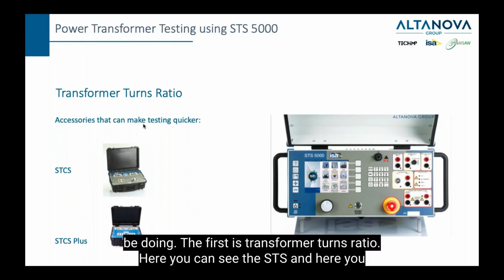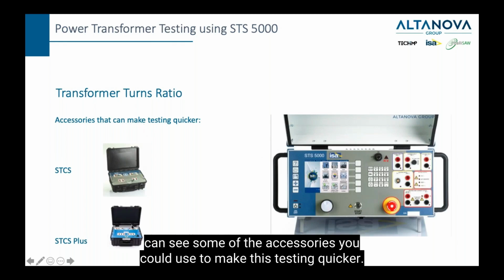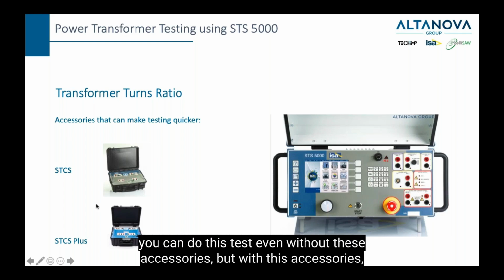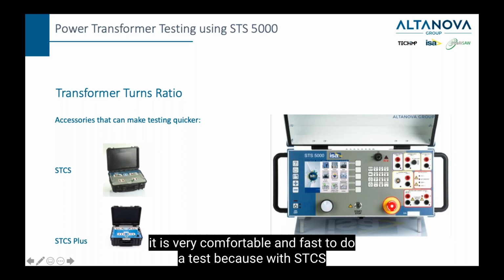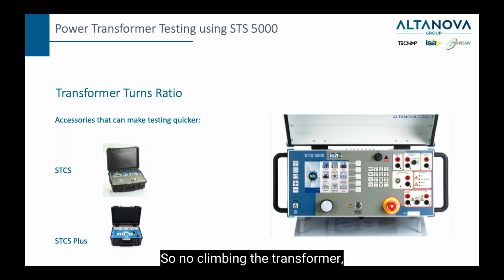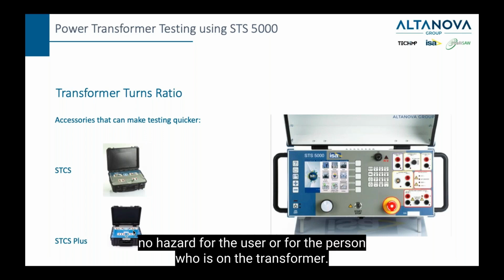So let us move on and start explaining what these exact tests are which we will be doing. The first is transformer turns ratio. Here you can see the STS, and here you can see some of the accessories you could use to make this testing quicker. It is not necessary. You can do this test even without these accessories, but with these accessories, it is very comfortable and fast to do a test, because with STCS and STCS Plus, you execute a one-time connection and you can do many tests. So no climbing the transformer, no hazard for the user or for the person who is on the transformer.